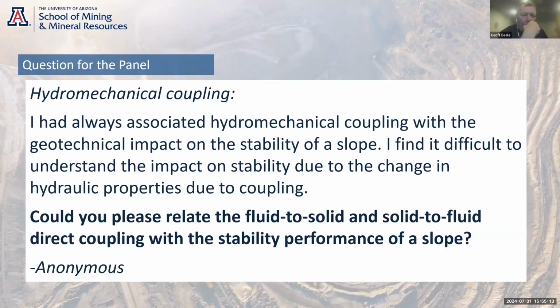I think, Lauren, the impact of stability due to a change in hydraulic properties due to coupling would be, as we were just talking about, when you have a set of joints or joint or slope structure parallel to the slope, it dilates, water can get in. The force of that water then becomes or can become a significant component of the force distribution. So if a structure dilates and you get a head of water behind it, it can lead to instability.